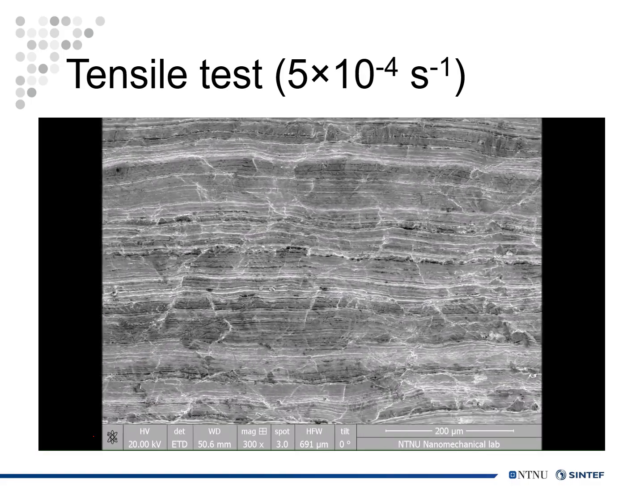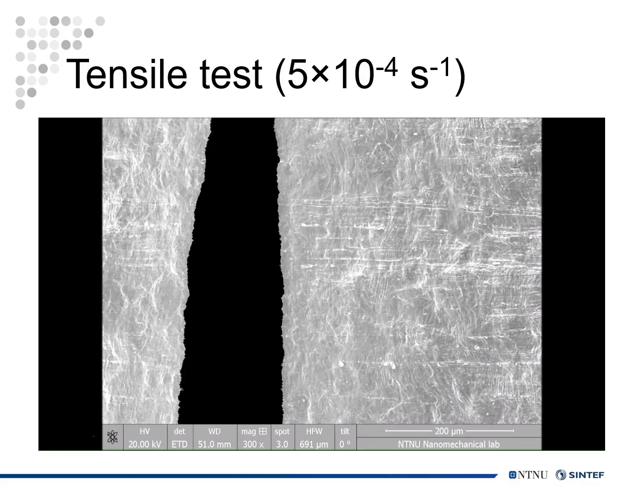At this magnification, we can see the deformation was not 100% homogeneous, but localized at some boundaries. The slip lines were mostly aligned in a direction perpendicular to the loading direction. The final fracture was overall straight and sharp, but locally in a zigzag-shaped sawtooth shape.